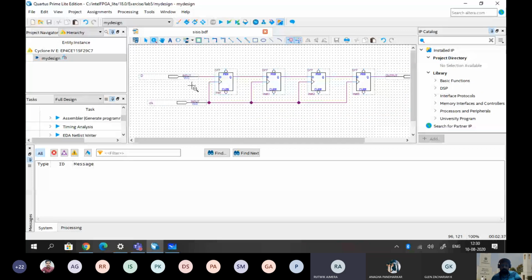If one netlist I have drawn, and I want to delete it, which button should I press? You want to delete something? Yes, sir. Suppose I want to delete the output. Just select whatever component you have, keep the cursor on it, select it, and then use the delete key on the keyboard. You can also right click, and you can delete it. Okay, sir. Thank you, sir.